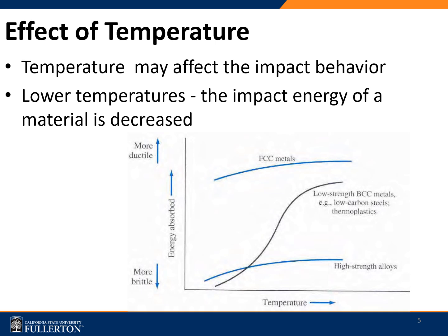So what is so interesting about this graph is that depending on the operating temperature, the way in which the material fails could change. And this is huge because now we need to factor in the operating temperature for such materials while designing them.